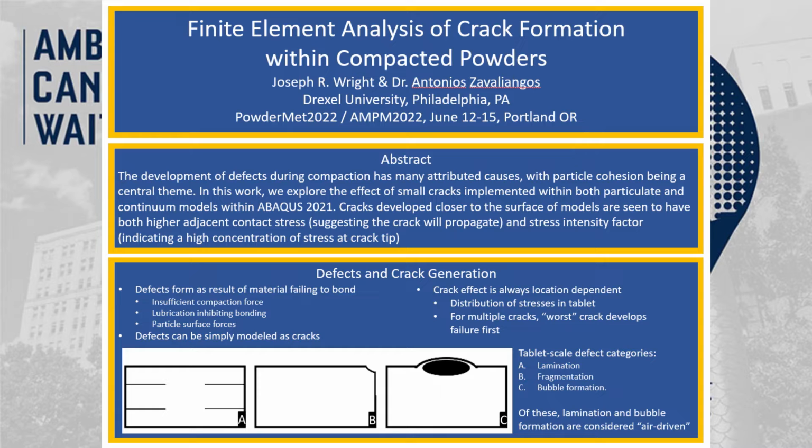We can classify tablet-scale defects as lamination, one or more horizontal cracks forming towards the top or bottom surface, fragmentation, material chipping off the edges where faces meet, and bubble formation. Literature suggests lamination and bubble formation are driven by the presence of air in the compacted powder.